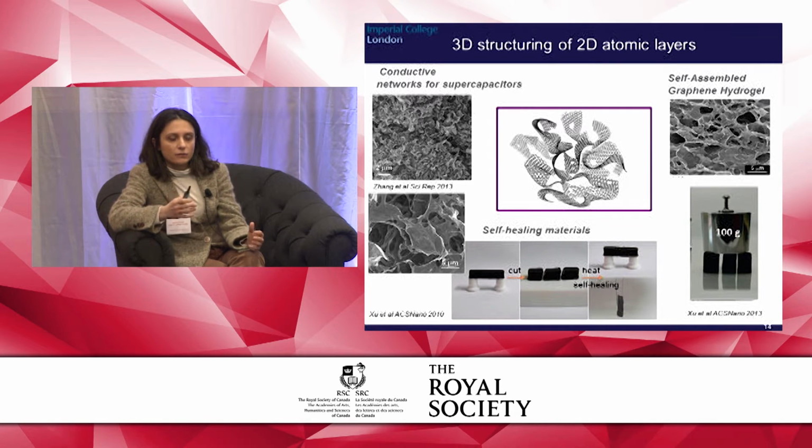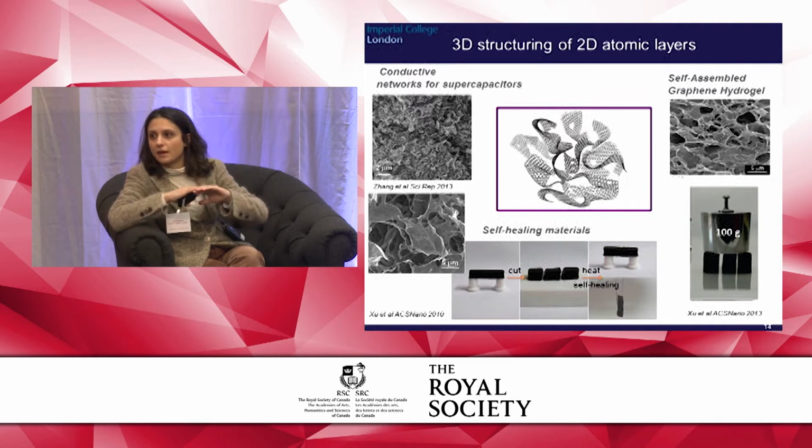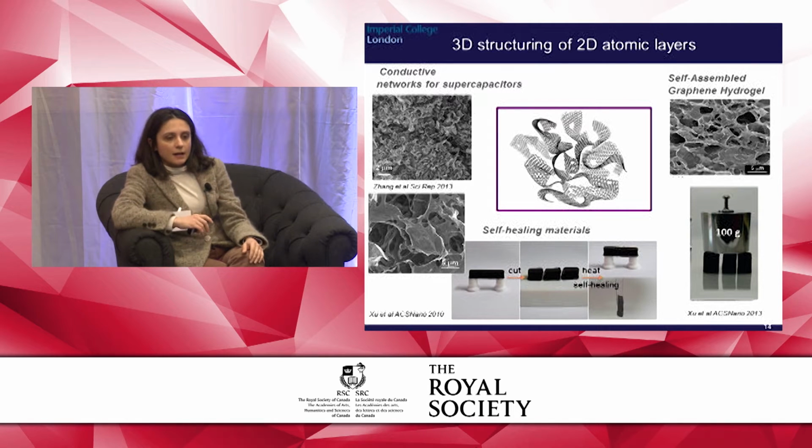So we can see we have all this random porosity, and we have this walls type of structure, which is formed by a few layers of graphene assembled together. And a major advantage of using graphene to make these three-dimensional constructs versus other polymers is, for instance, that those constructs are electrically conductive, while typically polymer constructs are not electrically conductive. And at the same time, they're mechanically much stronger than currently known constructs.